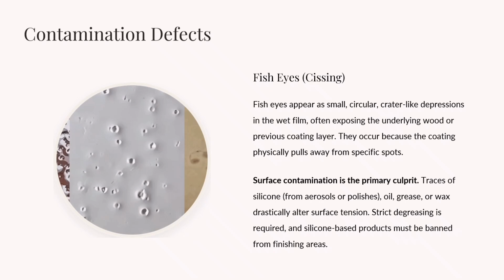To avoid this defect, proper surface cleaning and degreasing are very important. Also, silicone-based products should be avoided in coating or finishing areas to maintain a clean application environment.